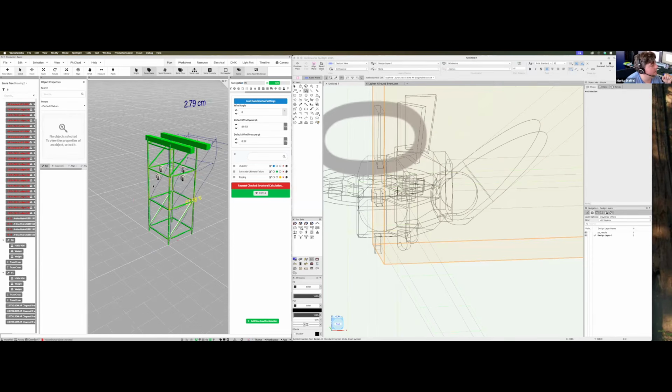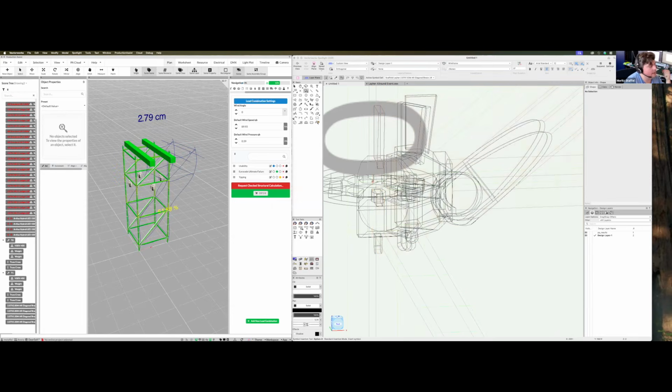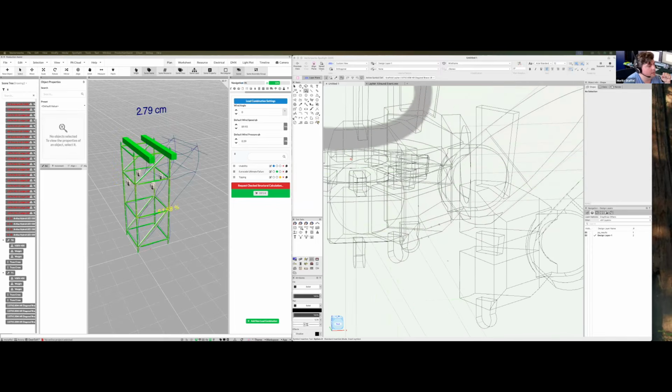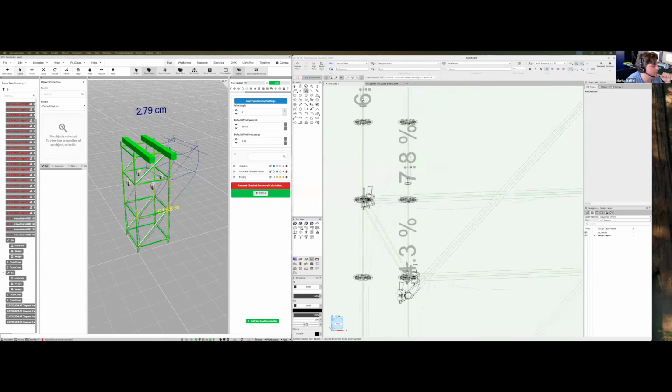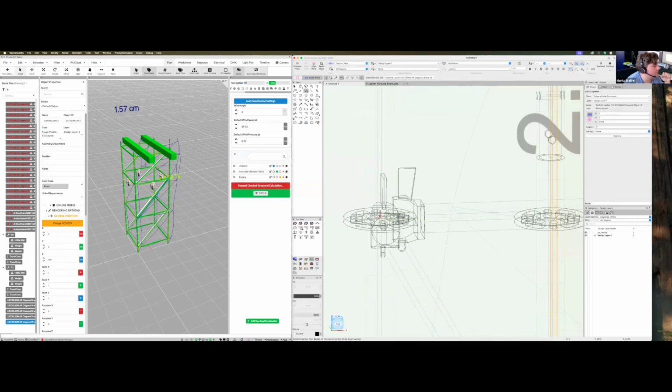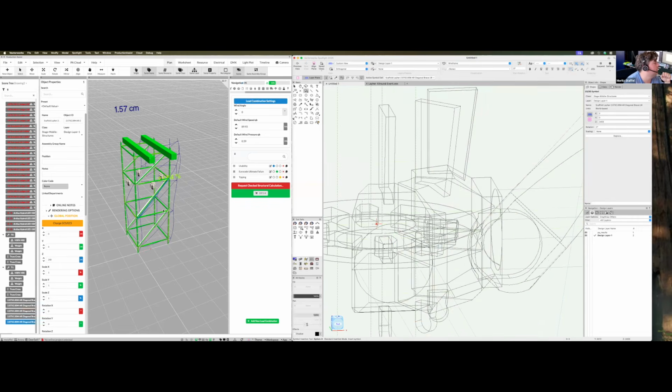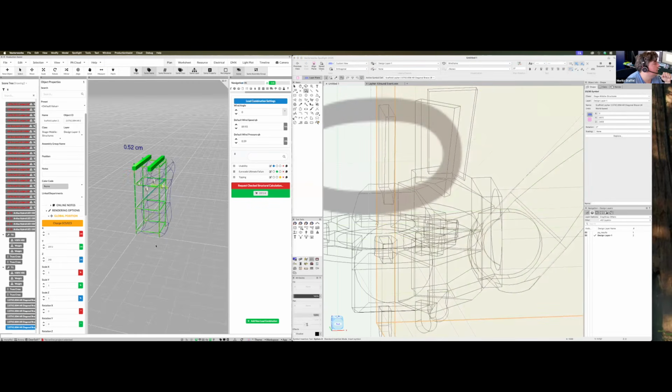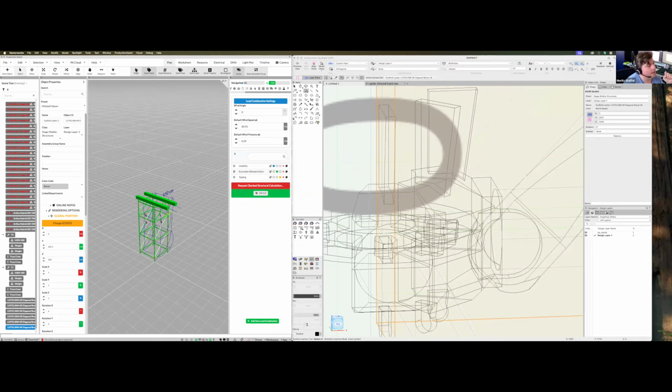So now the next step is I also want to add the other diagonals. So I'm going back in here, selecting the 2 meter diagonal again, moving a little bit up with this so that I'm here, clicking it at 1 and 2 so that I have this in here. Now you see it's good, and you see now it's almost straight. Only the bottom in here goes a little bit to the side, but this is totally acceptable. So this is fine in here for the actual calculation.